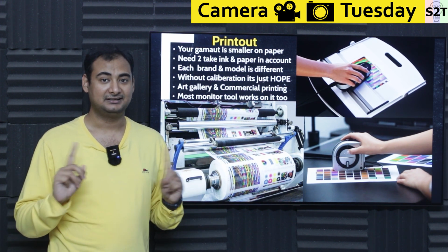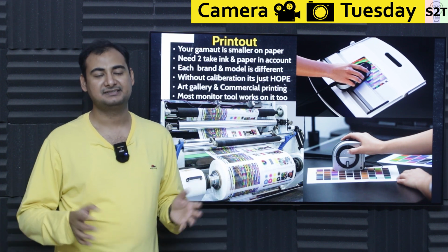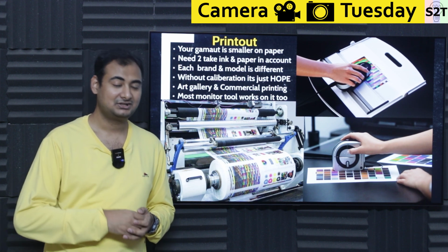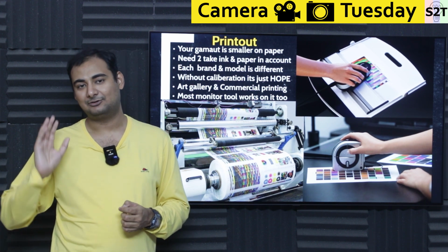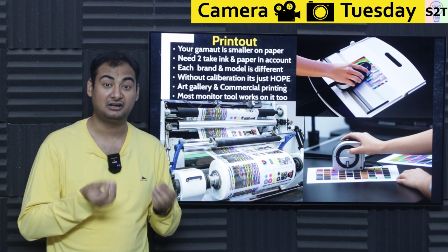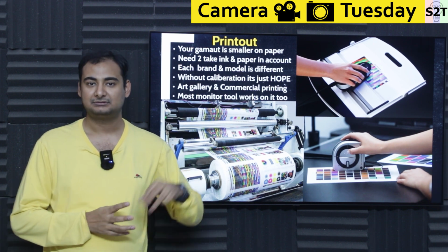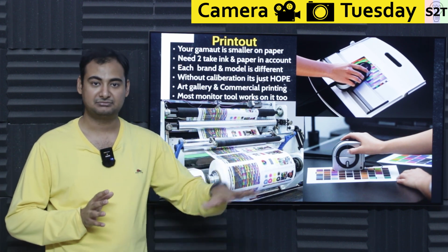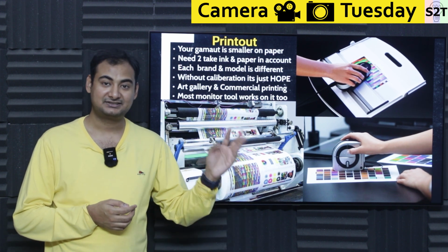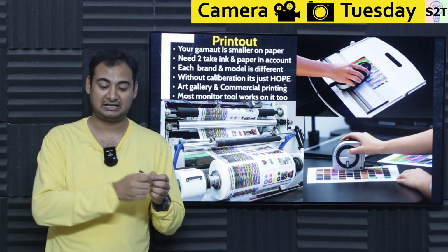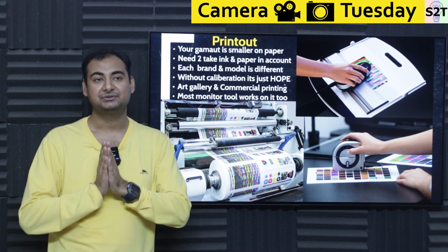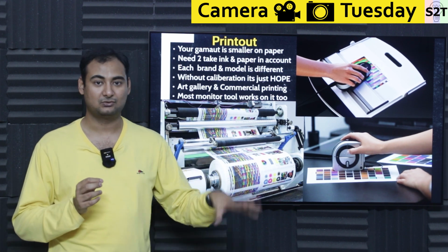Both are black. No, because for economical reasons, you ideally want to use pigment as much as possible, but they are idiotically expensive, though they are robust. So for document printing, black printing, they always use what we call pigment. For colors, you want to use dye. Why? Because dyes have color richness, they blend very well together. So the printer has this data where it's like, okay, I'm going to create the color to the best of my ability using the dye set. And sometimes if they are printing black, they might just use all three colors, because otherwise they have to switch the algorithm from dye algorithm to pigment algorithm. Yes, they are different. That would create an ugly image. So they just overflow the inks.